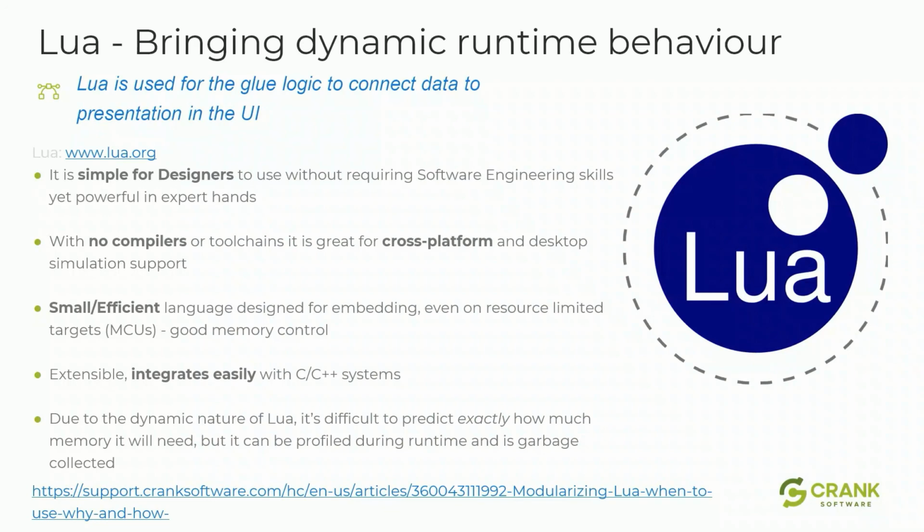So Lua is there, but you don't actually have to use Lua. We have alternatives for microcontroller targets. If memory is at a real premium, we have something called native C callbacks. So you're able to call out of your Storyboard model like we did with a Lua callback. There's a native C callback, so you can put in C code and remove any overhead for the Lua interpreter.